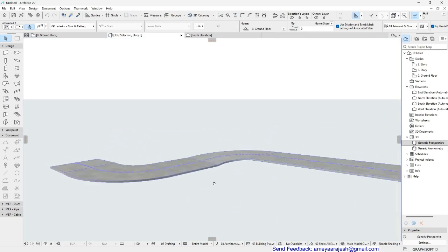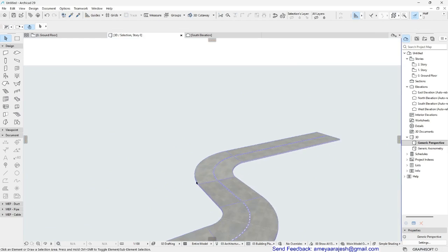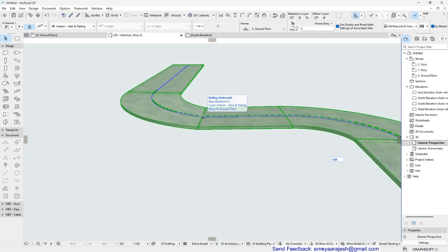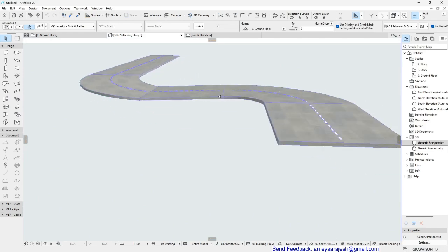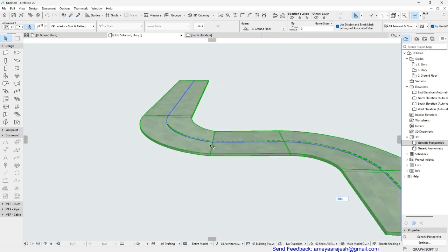That's it, nothing much. But still it is very quick, and what I can see, very helpful to achieve the required distances and the logic which you want to play. Say, for example, the gradient which you want to keep for the travel distance in 10:1 ratio. That means if I travel 10 meters, then my vertical distance traveled will be 1 meter. So according to that, you can start pulling up these things. Slightly here and there, if you want to adjust them for your design needs, you can do that.